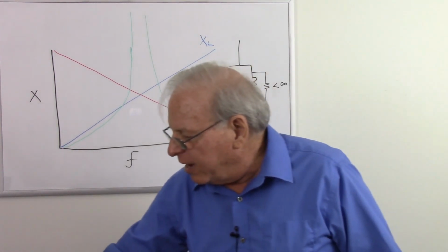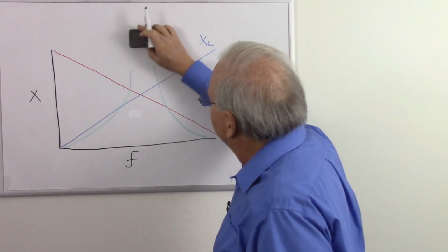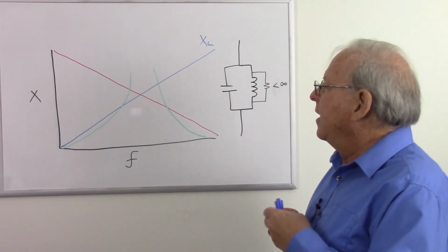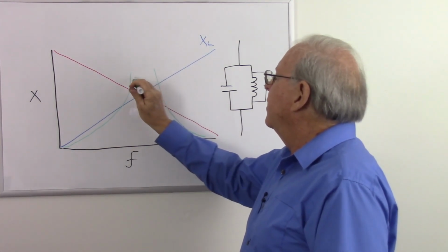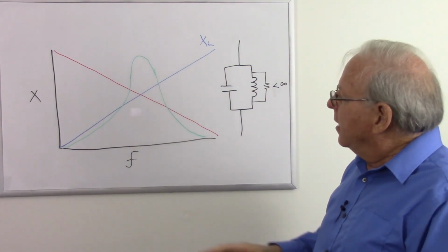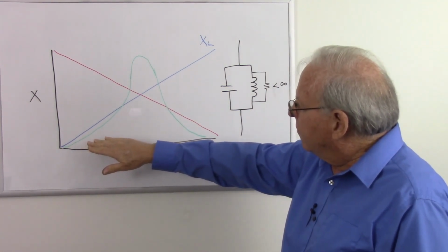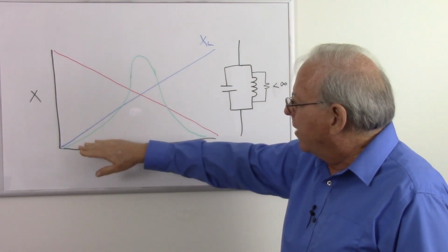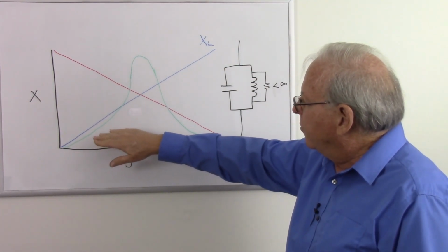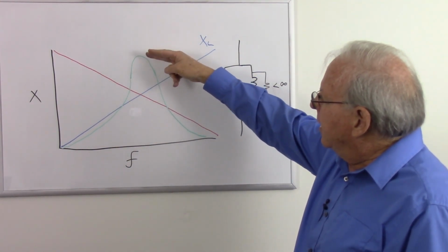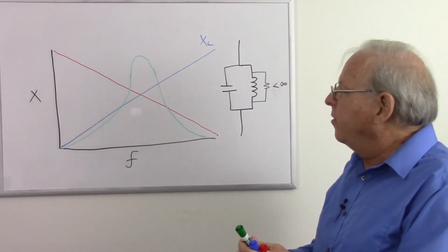And so in reality, this does something a little different, and that's that it gives us a curve that looks more like that. So that is the impedance curve of a capacitor and an inductor in parallel. Under practical application, we see that the impedance goes up and up and up, and then it's going to peak, and this peak is going to be what?